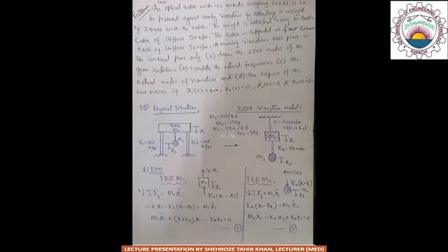Next we have another problem which states that an optical table with its contents weighing 147 newtons is to be protected against nearby vibrations by attaching a weight of 29.4 newtons to the table. The weight is attached using an elastic cable of stiffness 50 Newton per meter. The table is supported on 4 columns, each of stiffness 50 Newton per meter.